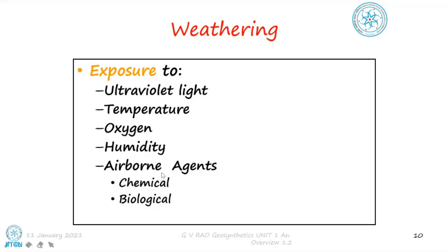The other important point is that after having said this is all subject to weathering, we should also keep in mind that polypropylene as a base material is found to be stable by and large from around pH 2 to pH 13. That means even very heavy alkalis and very heavy acids do not affect it. Even in landfills, with strong chemical leachates, it is not affected at all. And obviously it is not affected even by salt water, like in the sea.